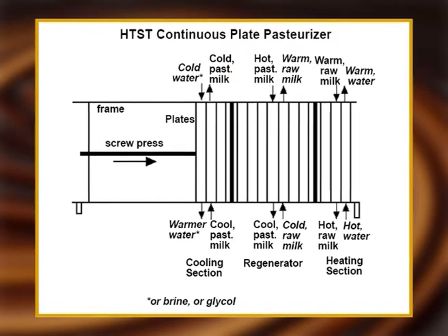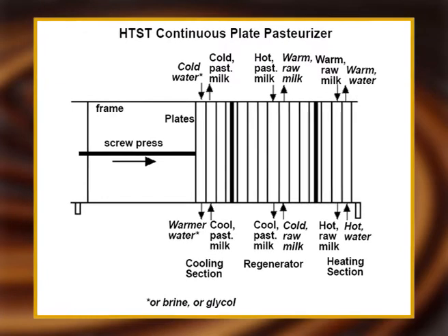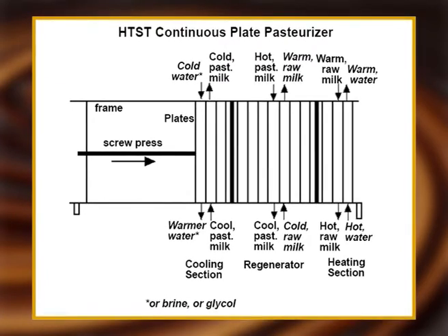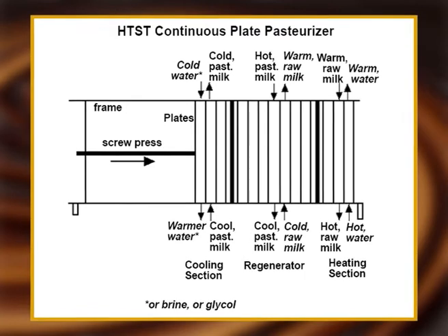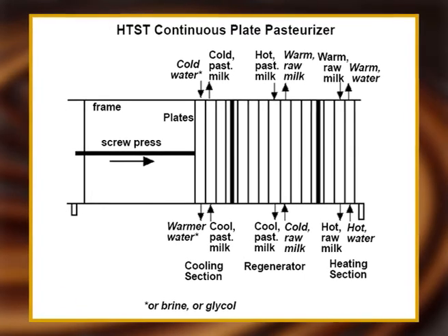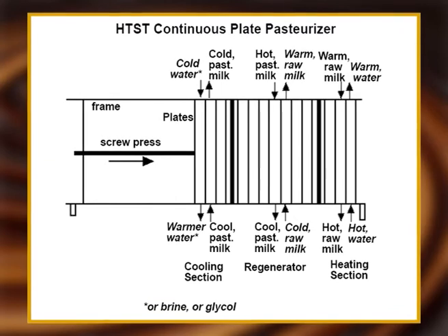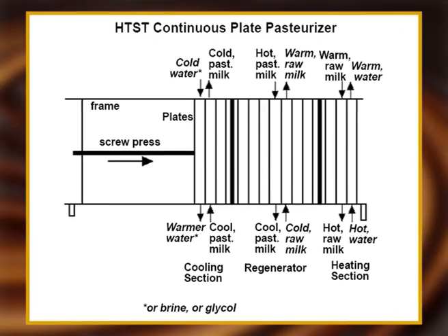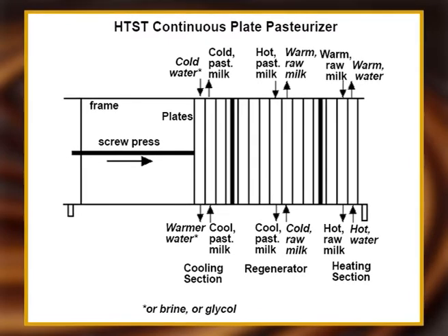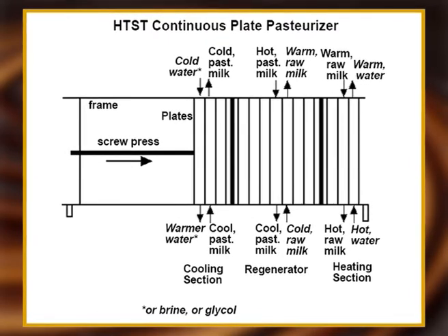Continuous pasteurization is usually performed in a high temperature short time heat exchanger following blending of ingredients in a large insulated feed tank. Some preheating to 30 to 40 degrees Celsius is necessary for solubilization of the components. The HTST system is equipped with a heating section, a cooling section and a regeneration section. The cooling section of ice cream mix HTST presses is usually larger than milk HTST presses. Due to the preheating of the mix, regeneration is lost and mix entering the cooling section is still quite warm.